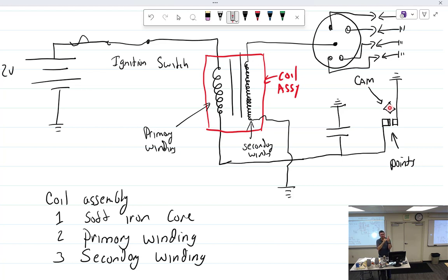It's all about timing. If you waited till here, it just doesn't work well. So it's compressing, ignition happens, and the piston continues to go up. By then, the fuel is burning, expanding, and it pushes the piston down. That's the power stroke. Then the piston comes up, pushes out all the nasty stuff, starts its trip down again. Up, now we go back to intake. So the piston's going to make 4 trips, 4 strokes: intake, compression, power, exhaust.